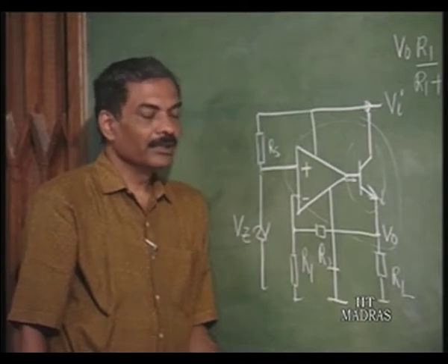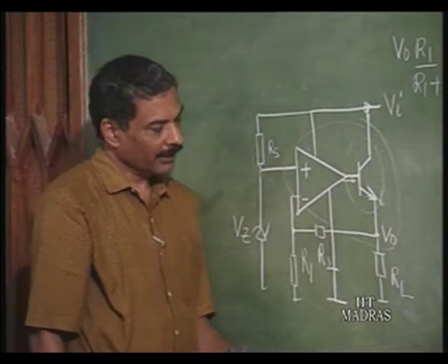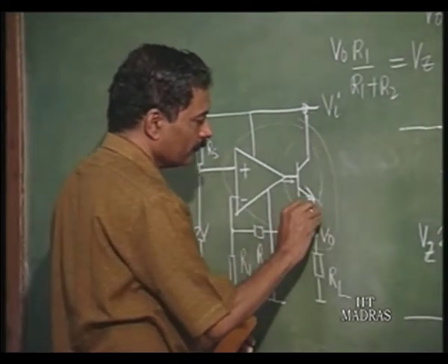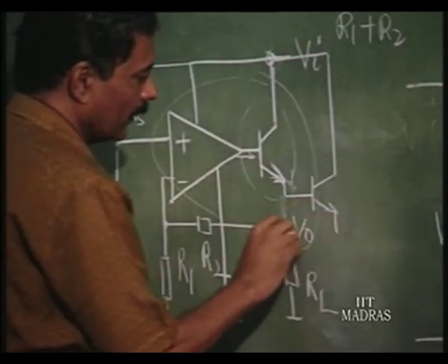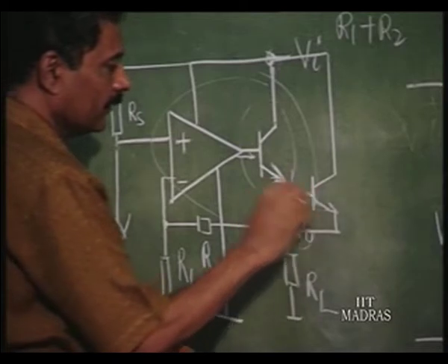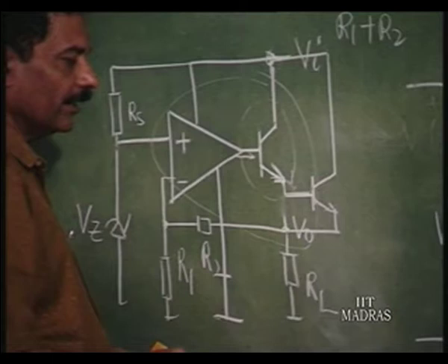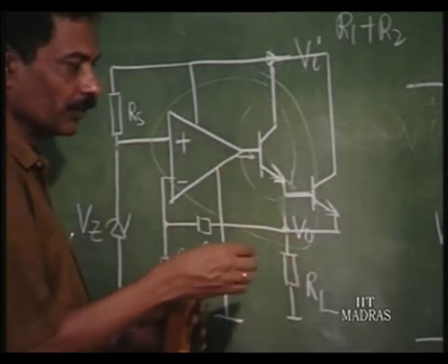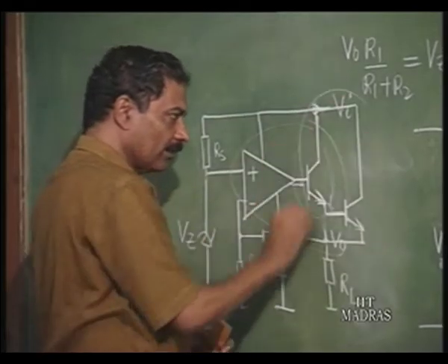Okay. If you think that the transistor rating is not greater than 1 ampere, then you will connect another transistor, right. This transistor is not adequate. Okay. So, I want higher current rating, you will connect these transistors in Darlington pair to boost up the rating of the regulator. So, these are all current amplifiers.